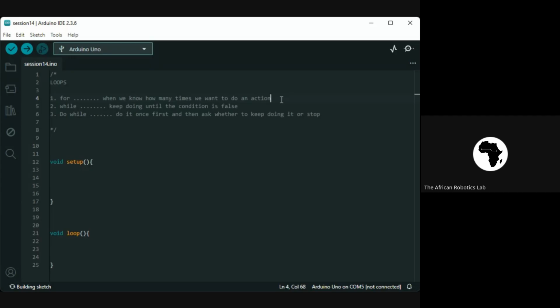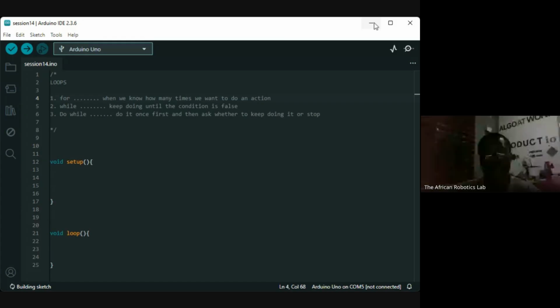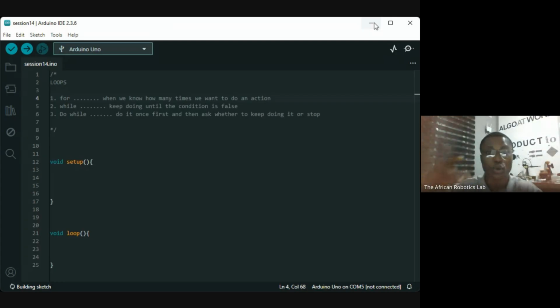And then apart from that, sometimes in a certain system, you want the sensors, right? You're going to appreciate this when you're building systems, especially battery powered systems. These sensors, some sensors, they consume lots of energy. If you have, let's say, about 30 sensors on a system, and all of these sensors are using energy, you're going to find that your battery is not going to last long.